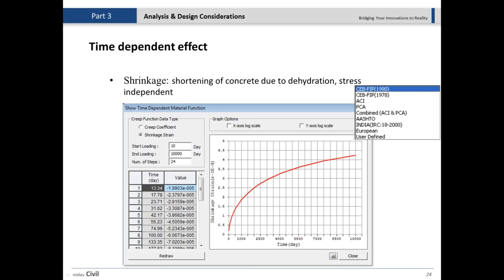It means at different ages they have different effects, and we have to be able to do all those calculations. For example, in Midas Civil we can get the results for different ages of the construction, and also as per the code, it asks us to check the final losses at the age of 10,000 days. So all of them could be effective to this structure.